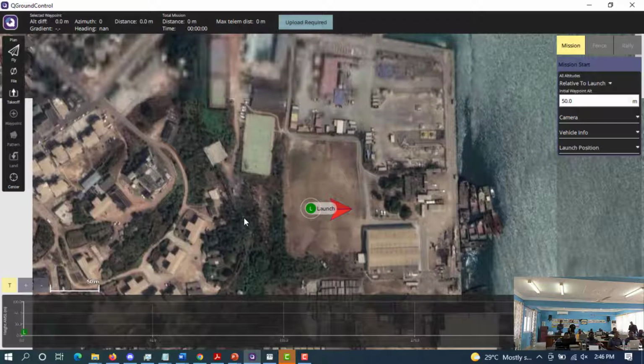In order to lose the height from 90 to 30, it will loiter, going from 90 through 60, through 50, and then it will try to reach the 30 meters and bring the aircraft to home. If this was 200, it would drop, drop, drop. But this loitering is a way of reducing power and approaching the landing spot where I want to get the aircraft.